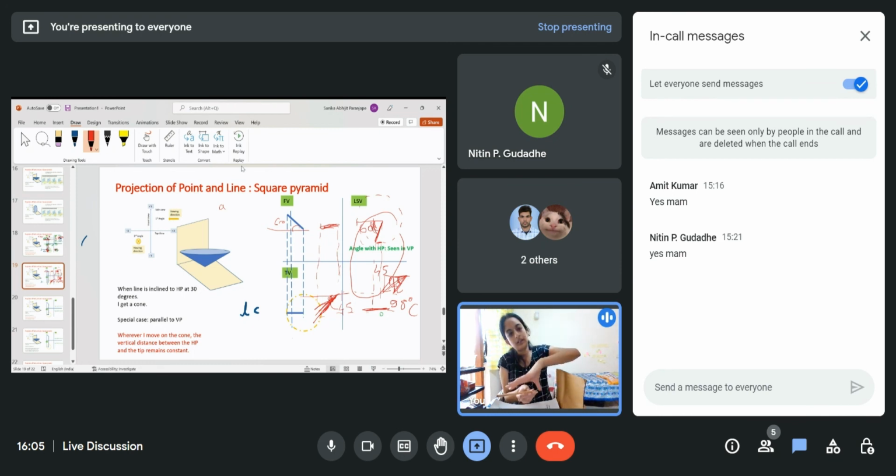So they will give you the apparent length in top view is this and the apparent angle is this. So from that you will be able to maybe construct this view. From this view you will get this view, and from this view you will have to come here and get the actual true length of the line. So that is why I'm saying that this is the straightforward way. I'm telling you that this is 45 and this is 60 and this is the auxiliary length. They might give you other parameters, they'll directly give you the auxiliary length here, and then all this knowledge will be very important, where you can see the actual angles and where you can see the auxiliary angles.